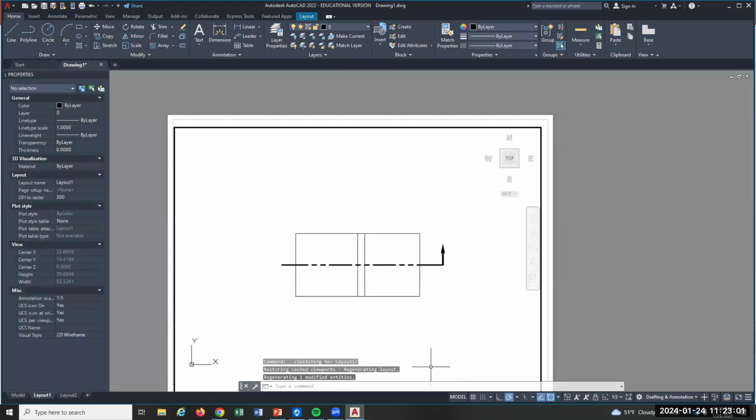So that's why I use polyline, because it's clearly a different line than a dimension line, right? It's thick. That's good. And then I would go and say, okay, I don't want to make that again. I would just copy it. And I actually have it as a block at home, so I never have to make that. I just pull in a block and place it. So we'll talk about blocks at some point. But you're gonna need thick lines. You're gonna need bigger arrows than your standard dimension. So there you go. All right.